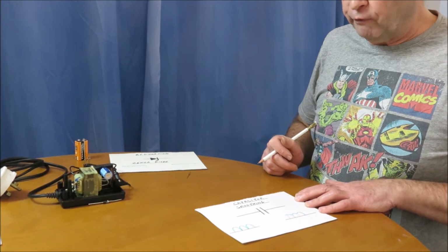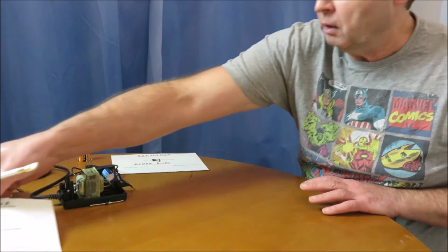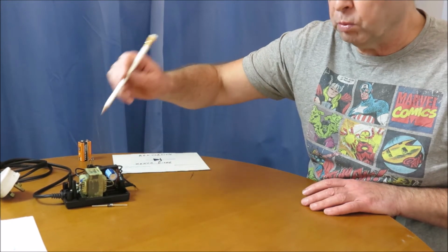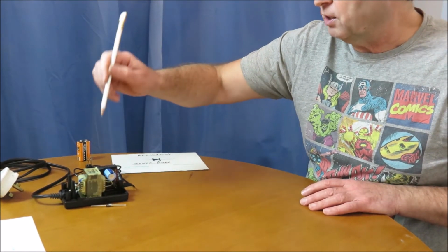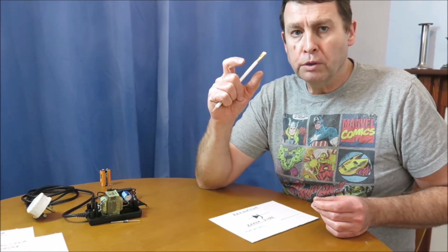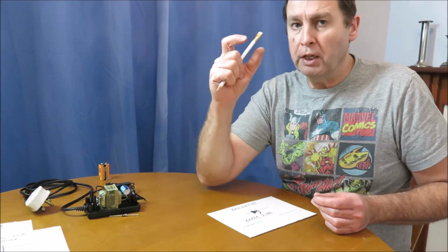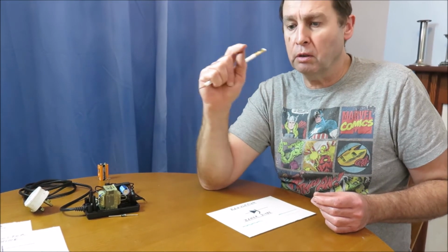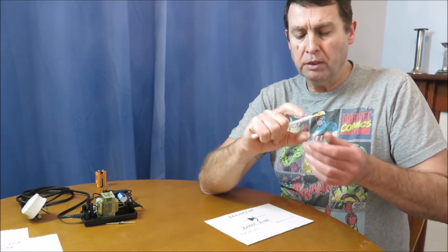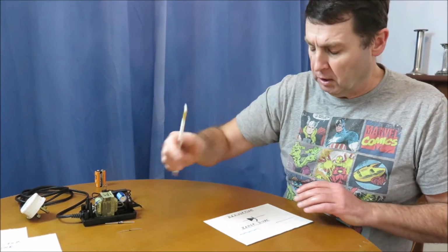Now that comes to the final section. The actual output of this with a little tiny bit of ripple on it is okay for the unit it was supplying. If we want a specific voltage, an absolute solid line voltage like we saw off the battery, we use one of these, and that's called a Zener Diode.